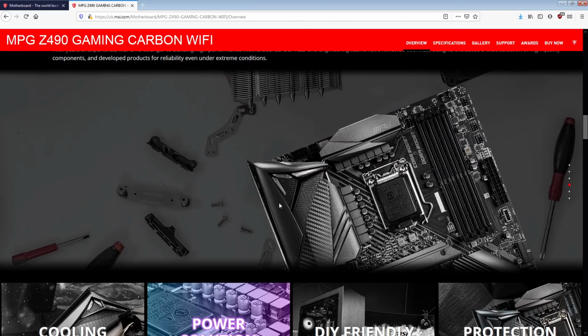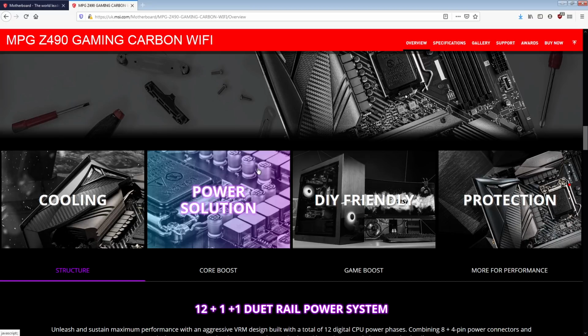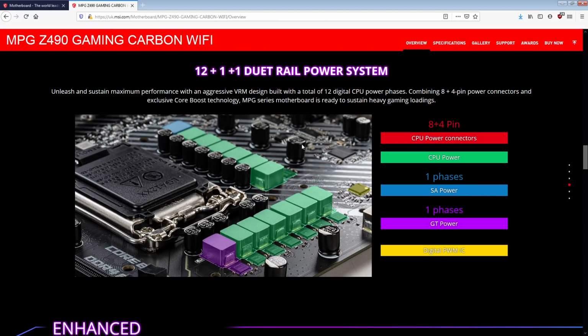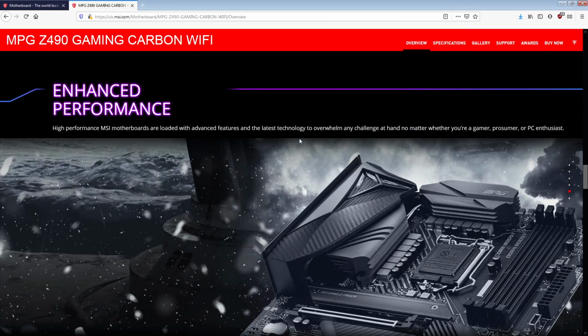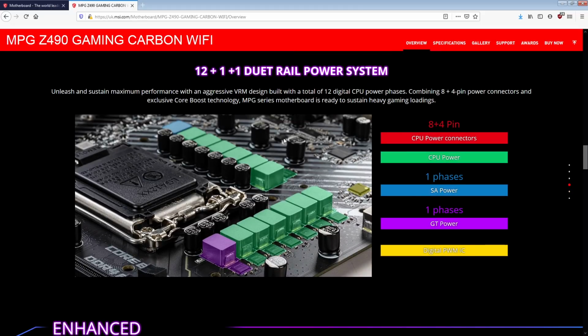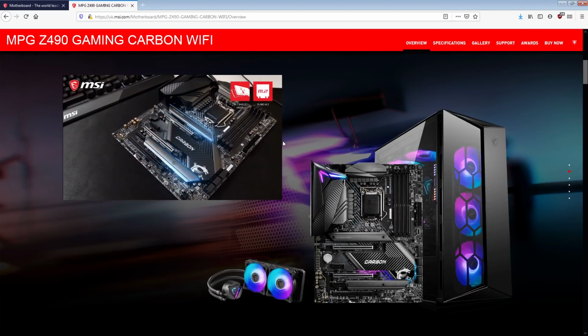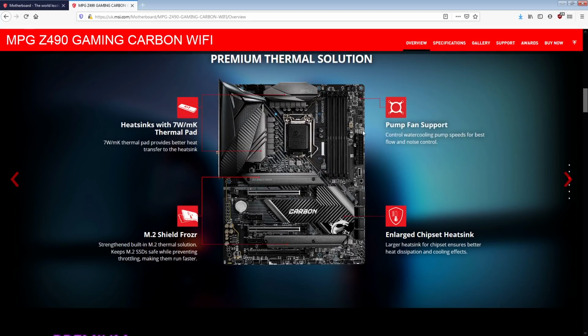The thing is, this price point is just ridiculously competitive, because Gigabyte has a 12-phase at this price point. Asus has a 12-phase at this... I mean, Asus doesn't do phases. Asus has 12 power stages on a 6-phase, if I'm not mistaken. And that's fine, Asus has their workarounds for the relatively low phase counts. Gigabyte does have the tantalum capacitors in the back of the socket. This is not a bad board, I'm just not sure I would choose this. All of them have troubleshooting LEDs at this price.